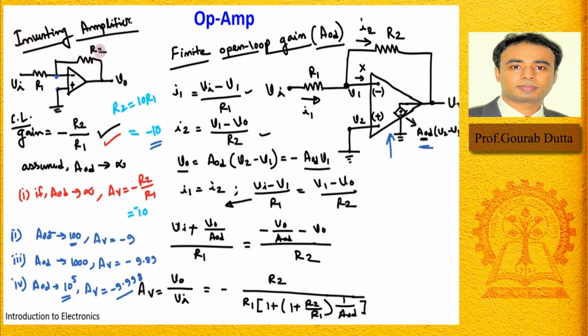we will modify a little bit about this R2, this place of this R2. Why we will do that? Because you can also assume from here. See, for example, let me pick another color. Yeah, this. So here you have seen the gain is minus R2 by R1, right? And suppose the R1 value is fixed at, suppose 10 kilo ohm, fine. And what you need is this gain to be 100, right? Then what should be the value of this R2? R2 should be 100 times that of this R1, right?